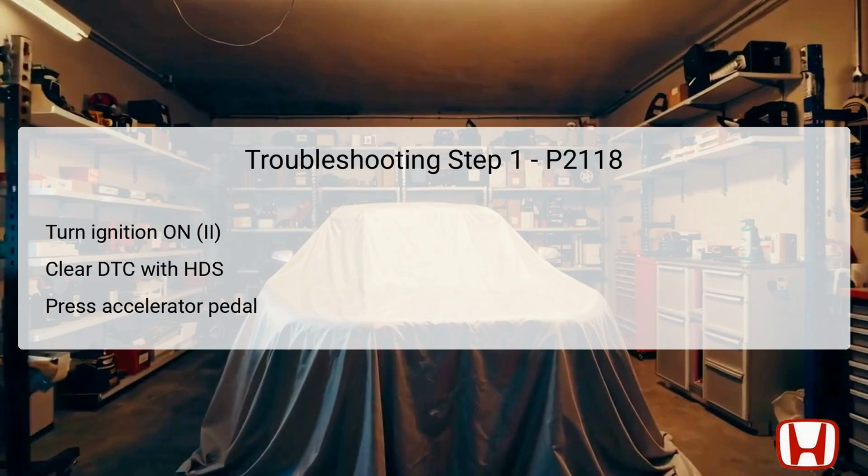If DTC P2118 appears again, it indicates that the failure has replicated itself under these conditions, and you should proceed to the next troubleshooting step. However, if no DTCs are indicated, there may be intermittent issues or poor connections that need to be further examined.